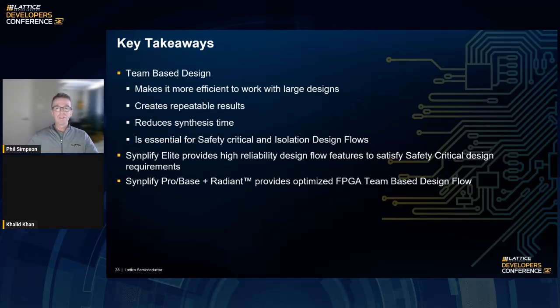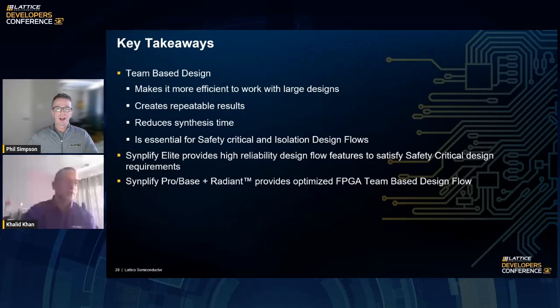In the rest of the designs, we really recommend that you only floor plan the timing critical blocks to preserve the timing on those blocks. By leaving the others as unfloorplanned, it provides a lot more flexibility for the place and route software to provide you with great results. But you can floor plan the whole device and have all of the blocks integrated, and the tool will support that.